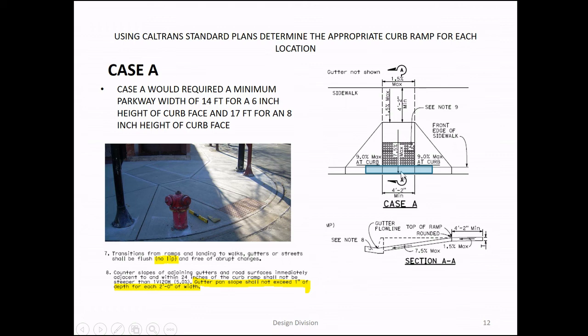Make sure that, again, if you're deviating from the Caltrans standard, you prepare a detail. And make sure again that water will flow through here, because this point here is what I have this blue line for. From this point to this point here, it's 2 feet on each side. It has to be 5%. So what they do is they raise this point out 1 inch.